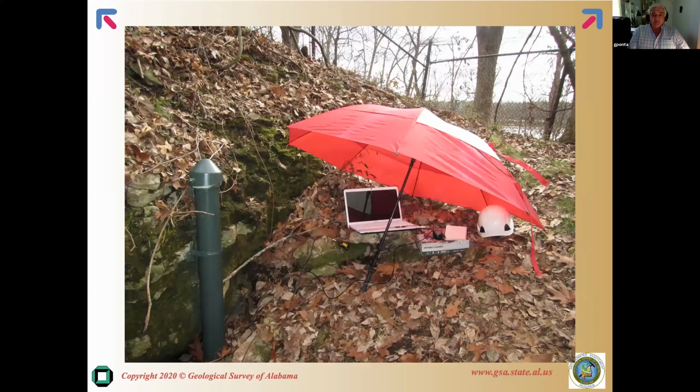In this cave, we installed a transducer, an OTT Hydromet transducer, and the end of it is in this PVC pipe, and on top is a device which transmits the data continuously to our office. It's a real-time monitoring well, or let's name it a well. We have temperature, conductivity, and water level data.